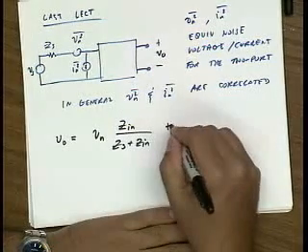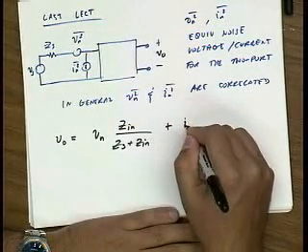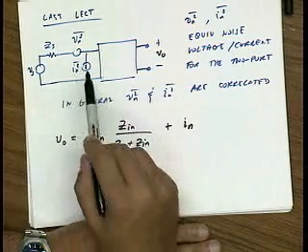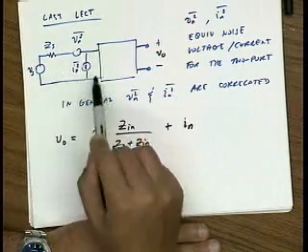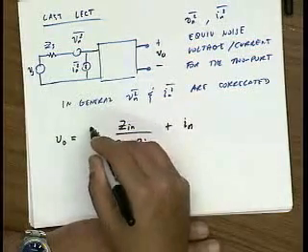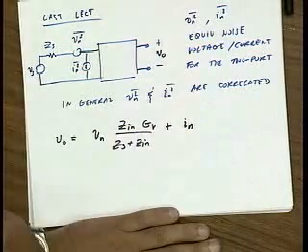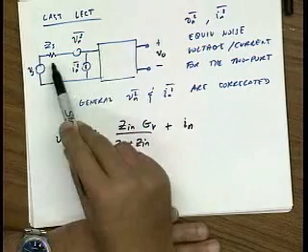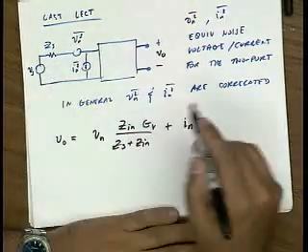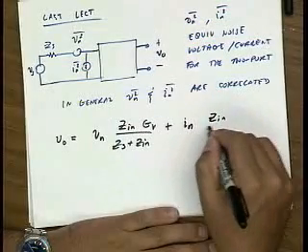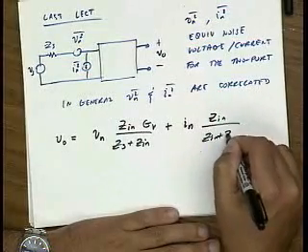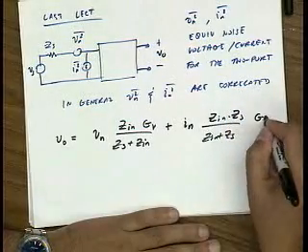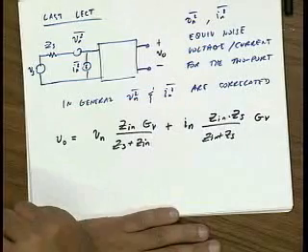And then to calculate the gain due to In, we can find the equivalent current going into Zs. So that would be a current divider times Zs, and now it's a voltage, and then times GV gives me the output signal.